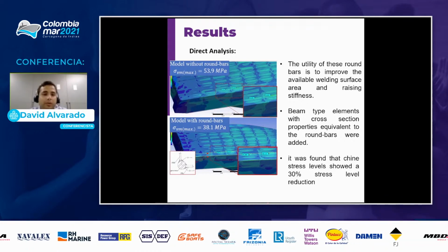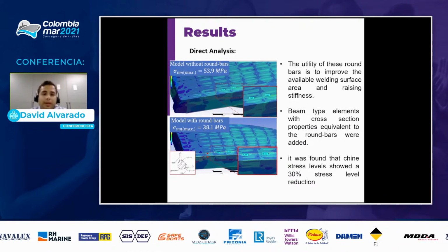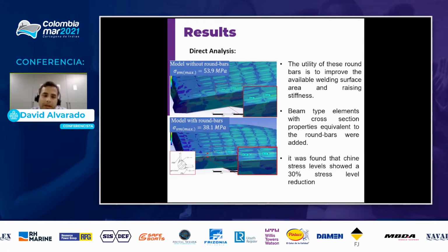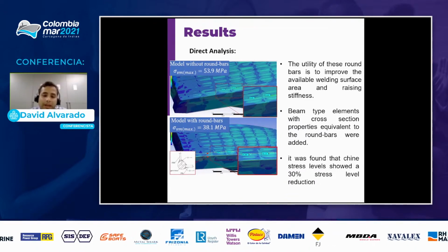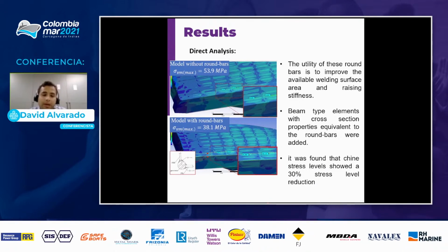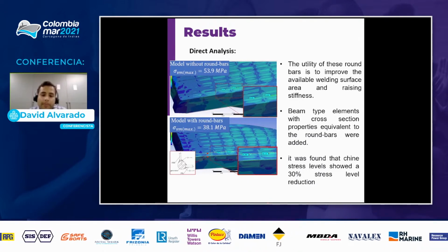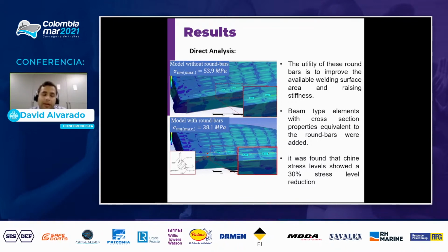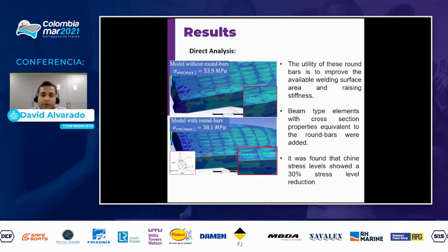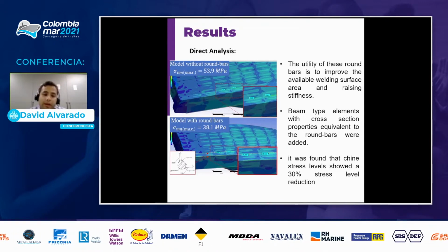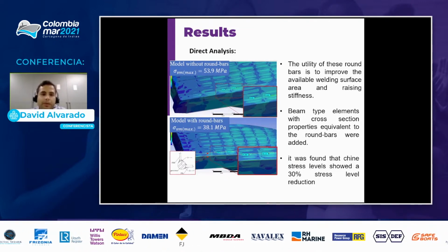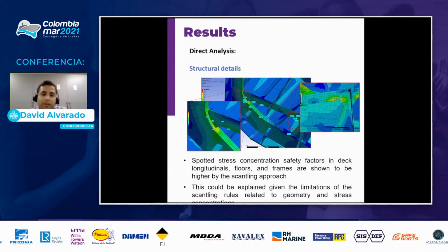We could see that we have a stress equivalent to 54 megapascals at the bars, and with the plates, it actually goes down. So with this improvement, we reach a stress that actually reduced down to 30% even with the 4 millimeter plate.